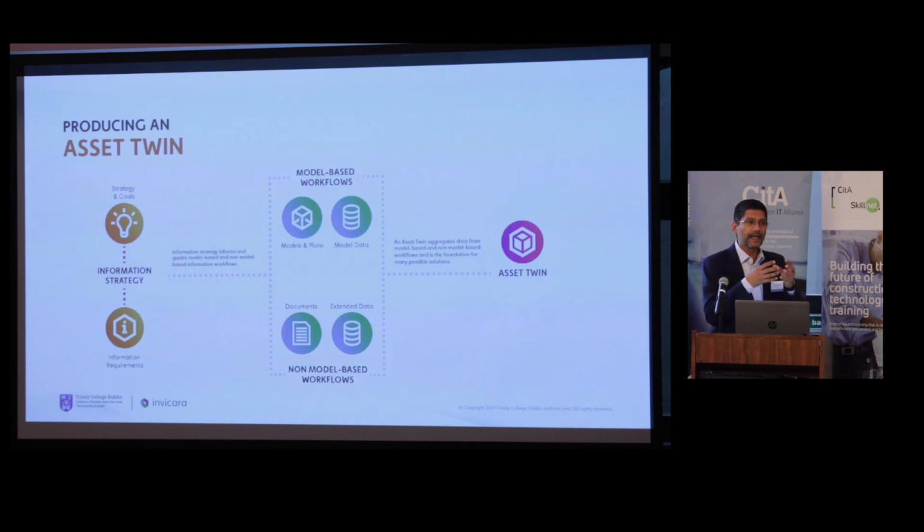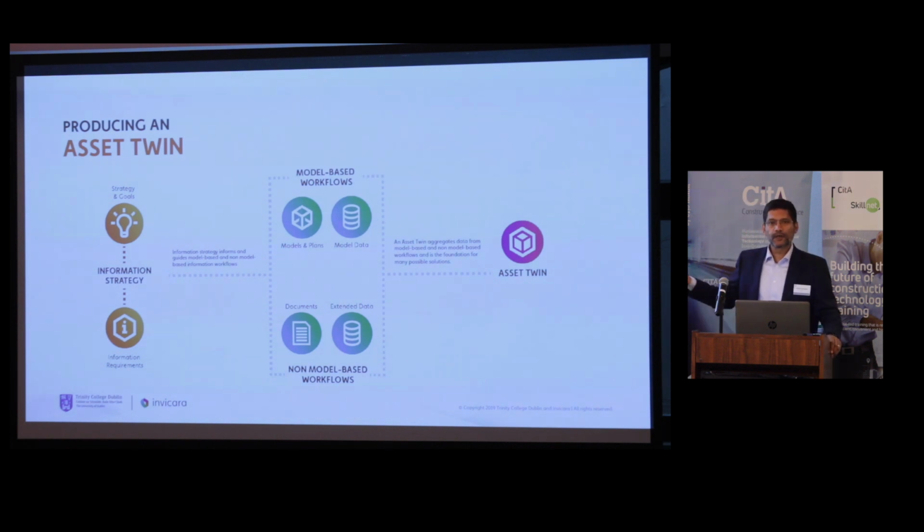I could be collecting type level information. Every instance of a pump of the same make and model has the same 8 or 10 parameters that the maintenance teams want. Why should that necessarily be put into the model? It can come through a simple data template, captured, transformed, connected back to the model. So there are a set of workflows that can be employed to streamline the process of information management. There are some data that's model-based and some data that's not model-based.